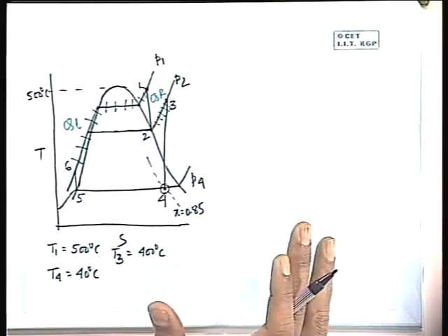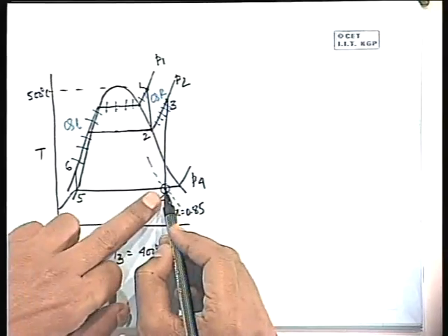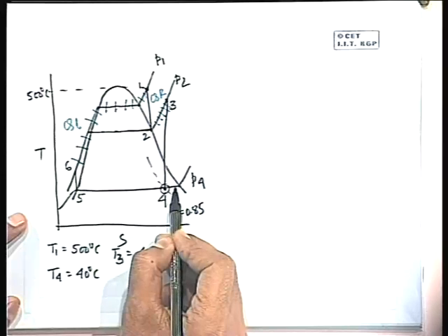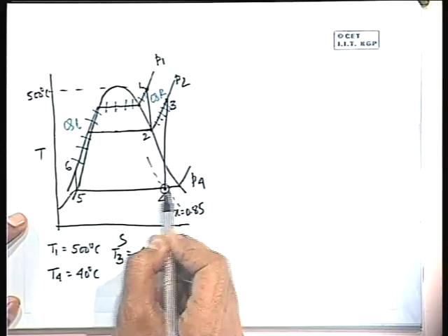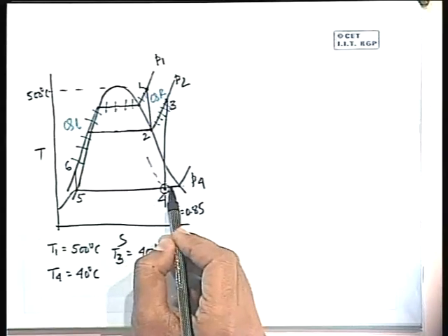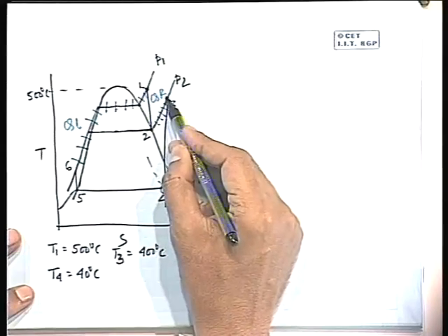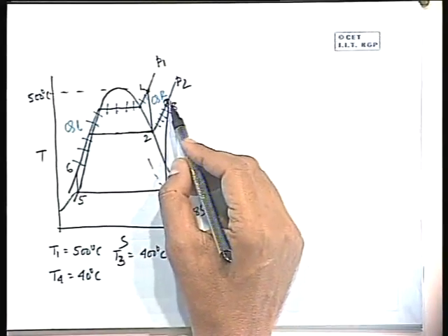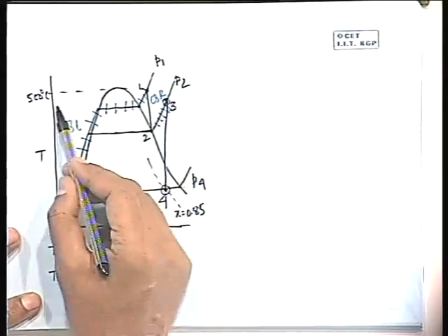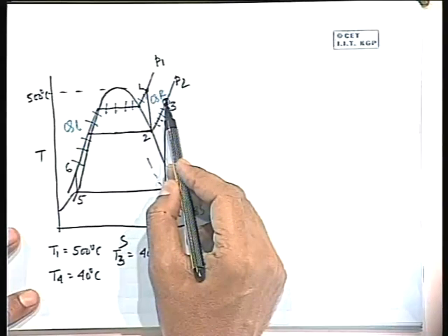Now if you see the steam table, you know the entropy of this point because you know the dryness fraction. At this 40 degrees Celsius temperature, you see the saturated steam table, then you can find these two entropy points, and accordingly the weighted average of these two with x will give you the entropy here. That means S4 is equal to S3. Therefore you will have to look in the superheated steam table at 400 degrees Celsius for which pressure gives this value of entropy.